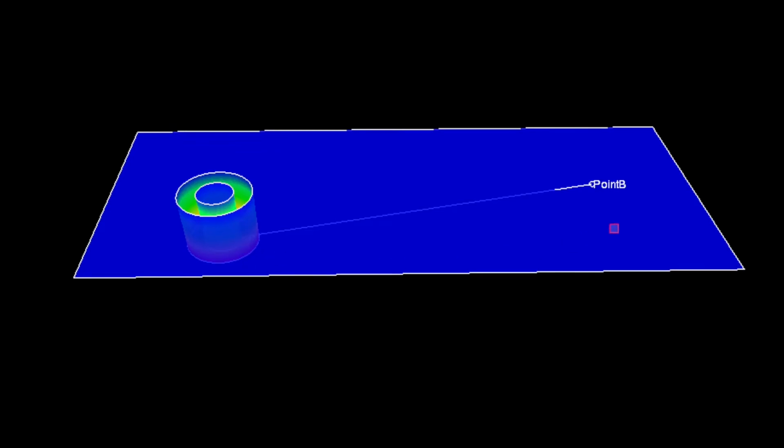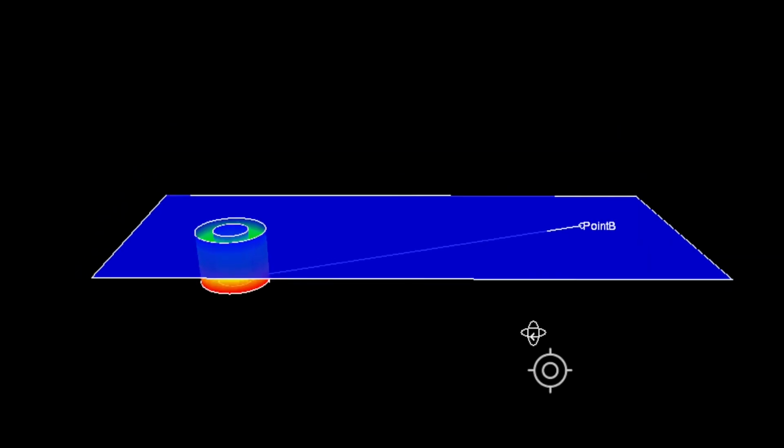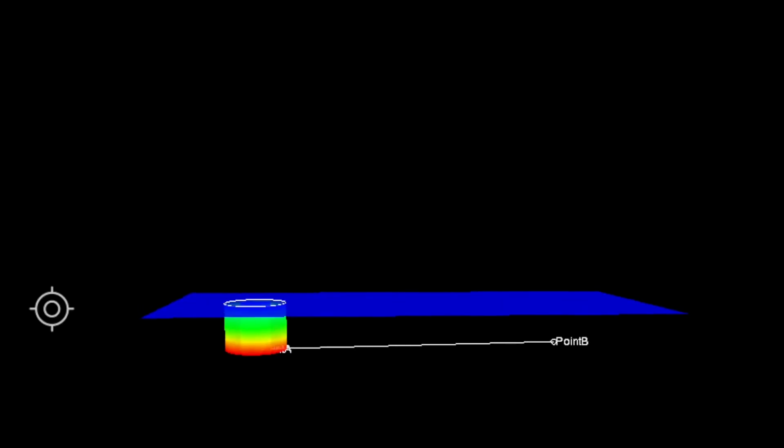Point A would be on grade and point B would be on the existing ground, as you can see here in this cross-section view. So what we can do is record point A on the invert of the pipe and then track to the second location and record that position for the bearing and length. We can then manually adjust the slope as it's called out in the plans like shown.